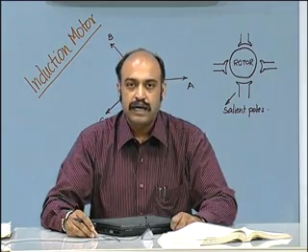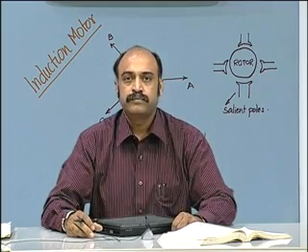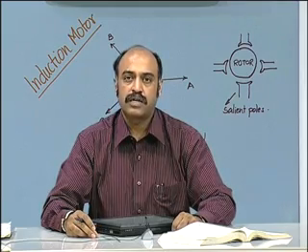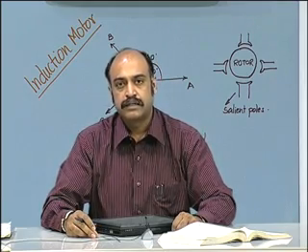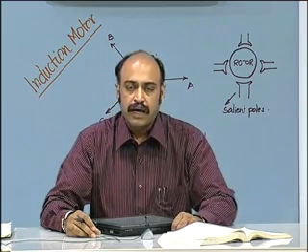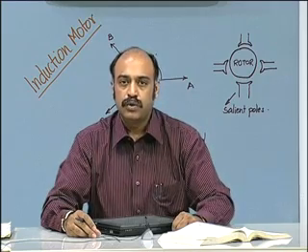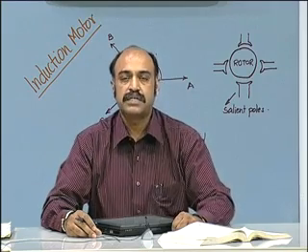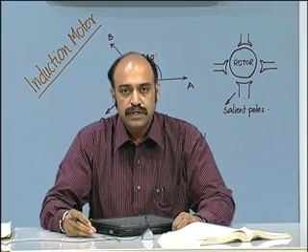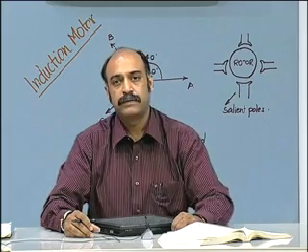We saw that the active power which enters the machine through the stator, and then some portion of the power gets lost in the stator as I square R loss due to the winding resistance, and then it goes to the magnetic domain, where you have the core losses due to hysteresis and eddy currents like in a transformer, and the remaining power goes into the rotor as the effective rotor power.